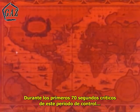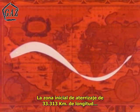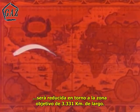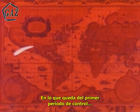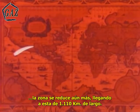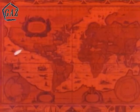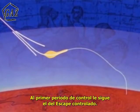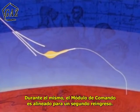During the first critical 70 seconds of this control period, the initial landing footprint, 20,700 miles in length, will be shrunk around the target to this 2,070-mile footprint. In the remainder of this first control period, the footprint will shrink further to this 690-mile-long area. The first control period is followed by the controlled skip. During the skip, the command module will be aligned for the second entry.